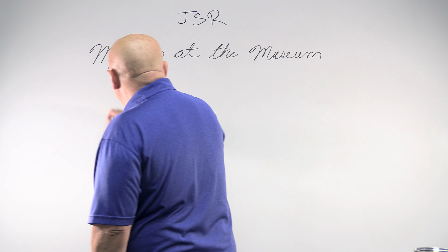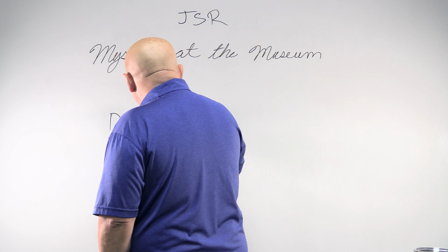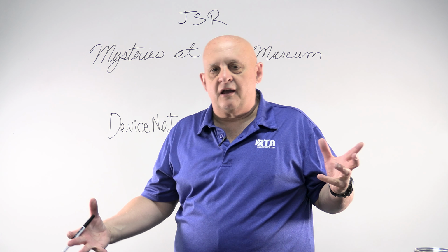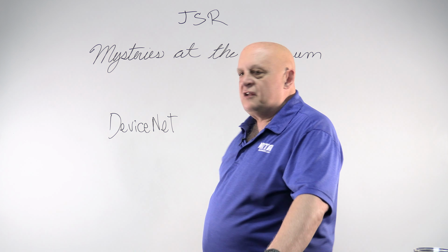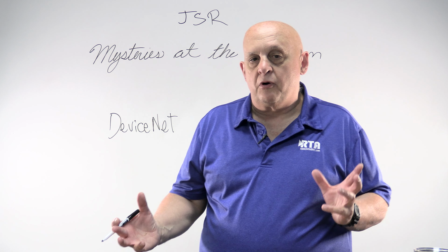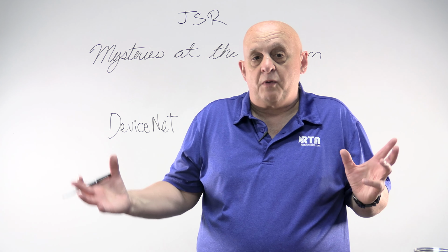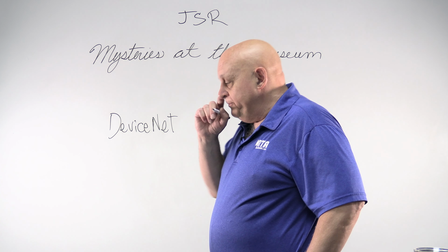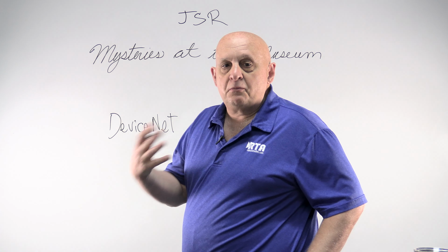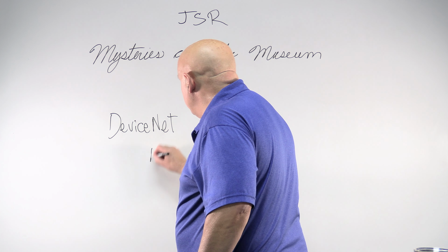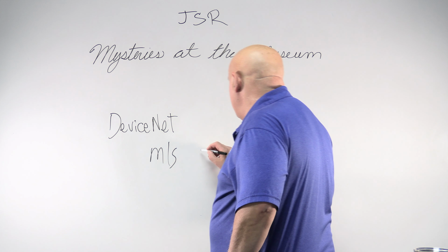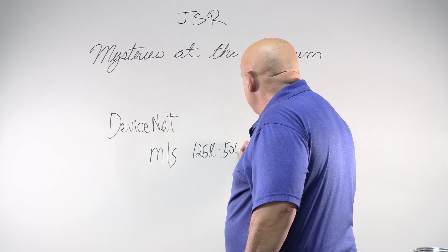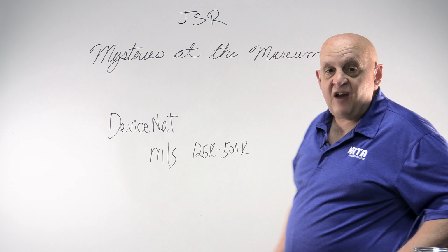So the first one I want to talk about is DeviceNet. DeviceNet is where I cut my teeth on non-serial communications. Now, this is the reason that DeviceNet was so special. It's a connection-oriented protocol, different than what we did before DeviceNet, a message response protocol. What's interesting about DeviceNet is it's not a terribly fast network. It's master-slave. It has probably up to, I think, 125K to 500K. So it's not really fast.